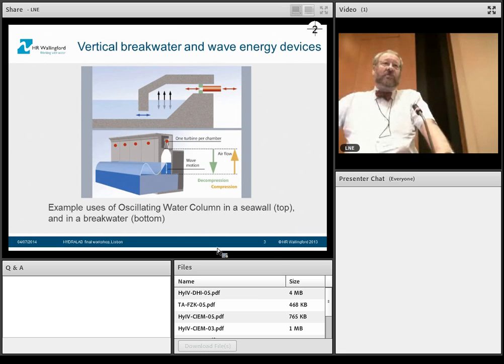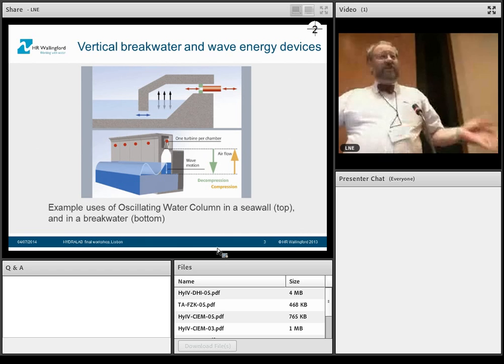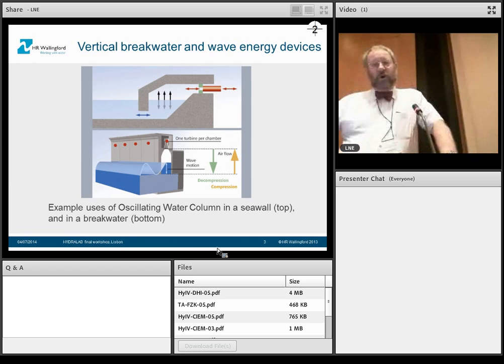And anyone who's worked with the reality of wave energy converters knows that there's a certain stage when suddenly the man from the steel fabrications or forgings throws his hand up as he's calculated just how little stress that he can accommodate under the fatigue loading. And anyone who's worked with real wave energy converters knows that almost always they have to re-engineer the moving and the static parts to accommodate much bigger stresses. So the big advantage of the OWC is to remove that.